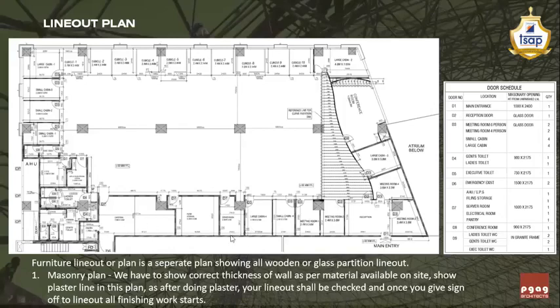And later, again the two rooms which have stagnant dimensions, and the third room, which is a cafeteria, is going to have a check dimension. Now to give this as a check dimension, again from the other corner of the RCC column, you have to give this dimension as a fixed dimension, so that he comes to know this while planning the brickwork of a toilet, because you never know from which corner he's going to start the brickwork.